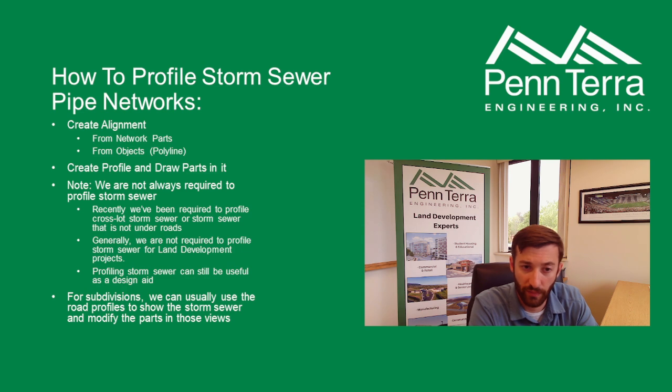And I added there, profiling storm sewer can still be useful as a design aid. It is helpful and it's quick enough to do if you want to have kind of working type profiles in your MD. You can do that, and it's useful for checking for conflicts and distances vertically between water lines, sewer mains, all that kind of stuff.